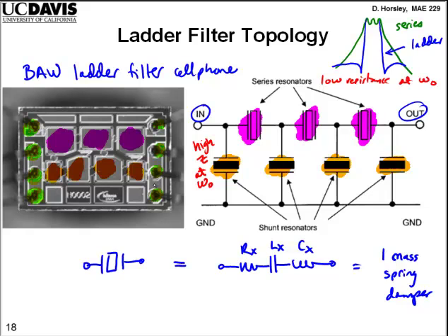And those are undesired. So there can be other vibration modes, and if those vibration modes are near where you're trying to operate the filter, they create spikes. You can see the resonant peaks, and they create what are called spurs. So they make these things oddly asymmetrical to avoid those spurs.